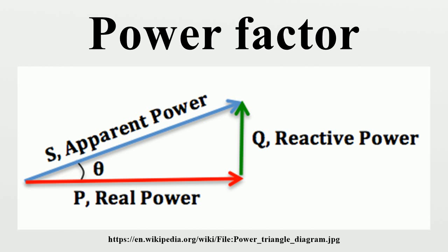Power factors are usually stated as leading or lagging to show the sign of the phase angle. Capacitive loads are leading, and inductive loads are lagging. If a purely resistive load is connected to a power supply, current and voltage will change polarity in step. The power factor will be unity, and the electrical energy flows in a single direction across the network in each cycle. Inductive loads such as transformers and motors consume reactive power with current waveform lagging the voltage.